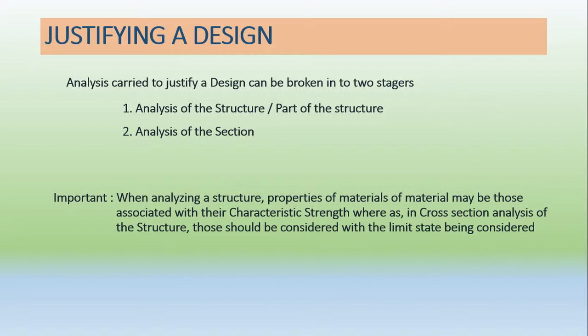Another important thing that the code mentions is that when analyzing a structure, the properties of materials may be those associated with the characteristic strength. That means when we analyze a structure, we use material properties such as Young's modulus, all associated with the characteristic strength of that material.